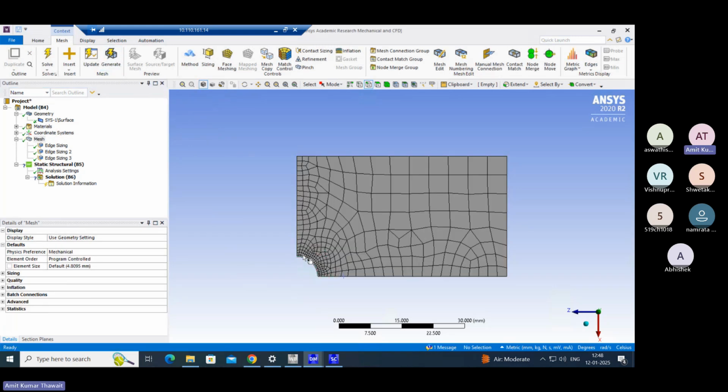Now here you can see the mesh is refined near this wall or near this curved surface. Okay, and also it is refined along this location, along this line, vertical and horizontal. But still what is happening here is, when you see from this mid location, your element size is constant throughout to this end. Similarly in this vertical line, from the mid or before that also, you have uniform element size.